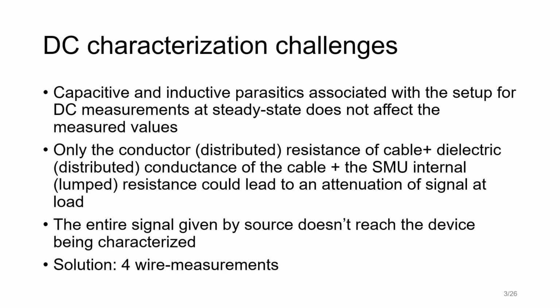While performing DC characterization of devices, one need not worry about the inductive and capacitive parasitics associated with the setup of the DC measurements, because at steady state, such reactive components would play no role and thus they will not have an effect on the output.